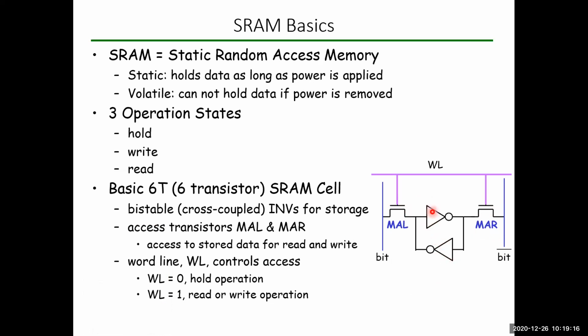So we know that if I need to design a NOT gate with the help of CMOS logic, then definitely I need two different transistors. So this NOT gate has got two transistors, and even this NOT gate has got two transistors. So ultimately, in this particular figure we have 6 different transistors. So we call it a 6T SRAM cell.